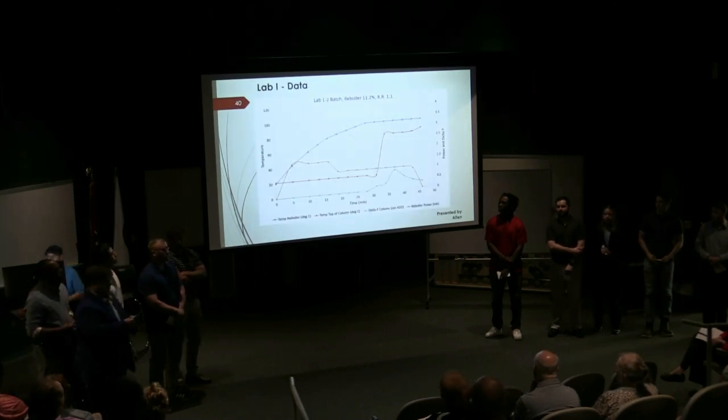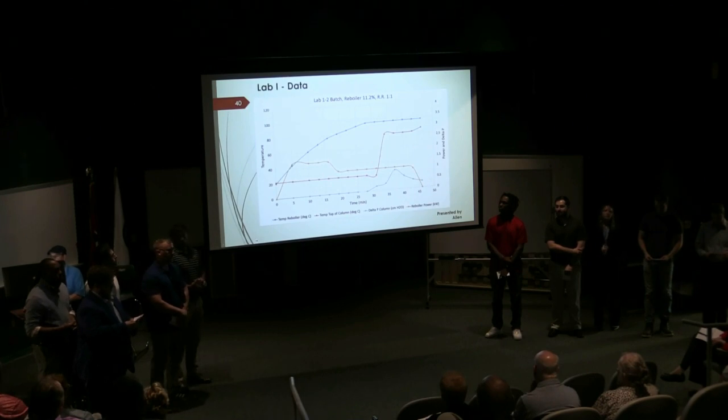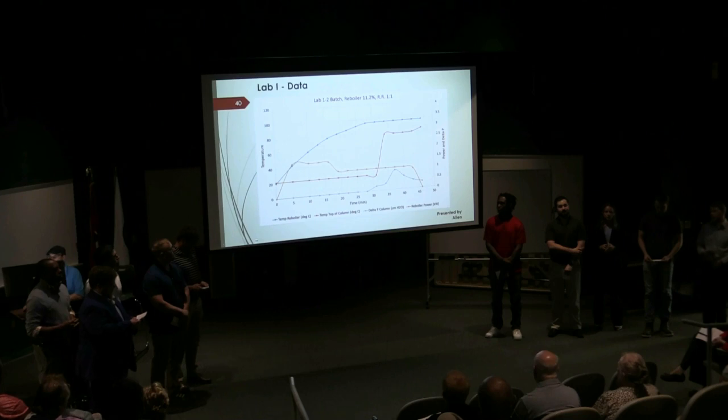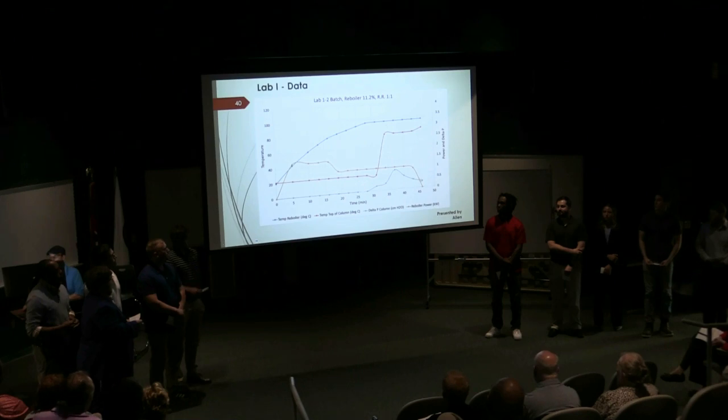In run 2, we raised the reflux ratio to 1:1. As you can see, the reboiler temperature increased slightly, for the reasons pointed out earlier. The temperature at the top of the column did not remain stable. Due to this, we were unable to collect product for 15 minutes. If you look at the delta P curve, we have an indication of our highest collection rates at the beginning, and tapered off as the run went on.